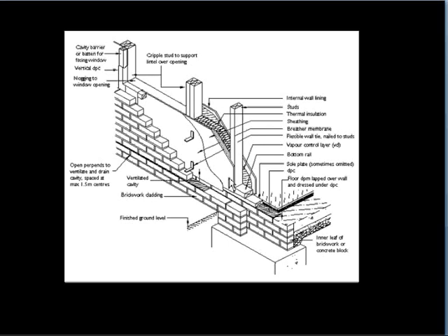In terms of the other structural element, outside the structural frame you'll have a sheet of material, usually a sheet of plywood or OSB board, which provides a rigid connection to the frame to stop it from moving from side to side. Because it's a cavity wall construction, we've got a sequence of wall ties that are connected to the timber studs, and these penetrate across the cavity and brace the wall itself.